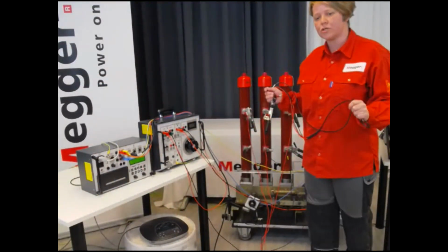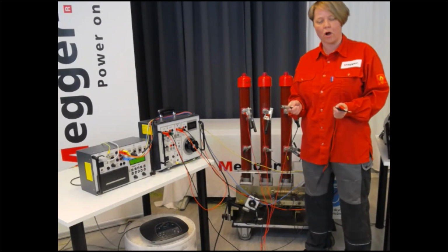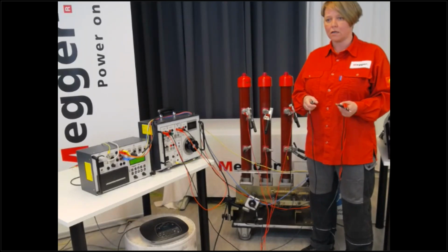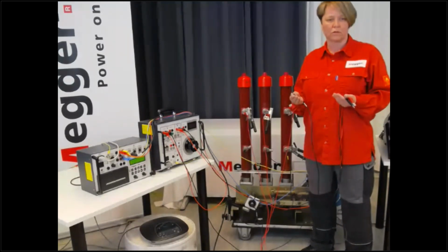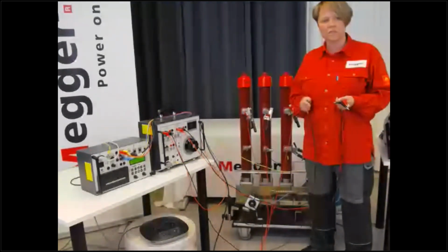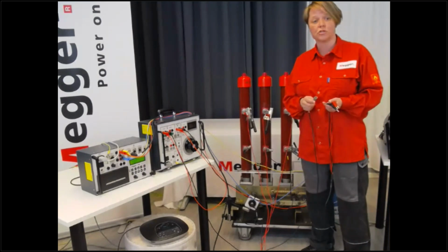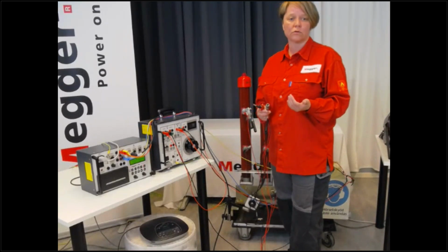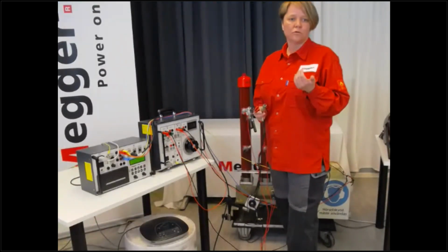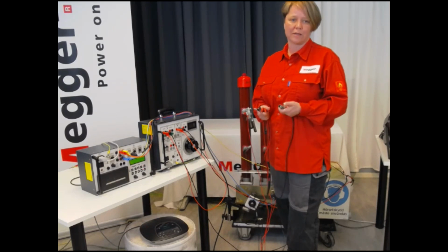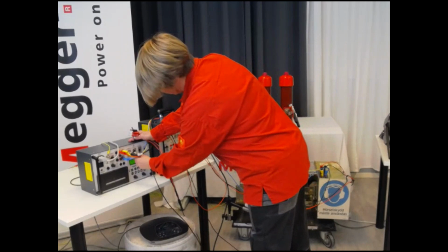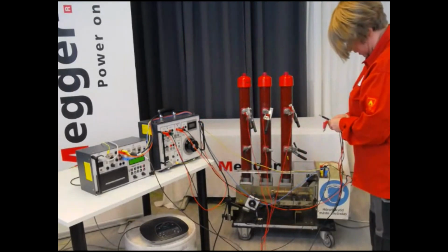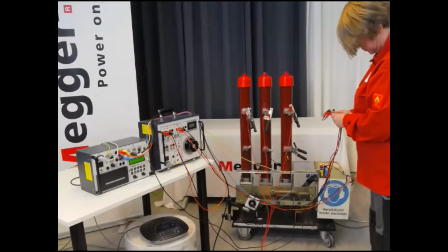I also want to measure the auxiliary contacts. Auxiliary contacts, Marius mentioned before, are the contacts which are, as you could say, relay or control contacts in the circuit breaker. And the ones we're interested in are the ones which are in the coil circuit. They are the most important ones. They're really important so you don't burn coils, and also you must make sure that they are following, because they are like a protector of a coil. I connect to the auxiliary outlet and I connect to the circuit breaker.